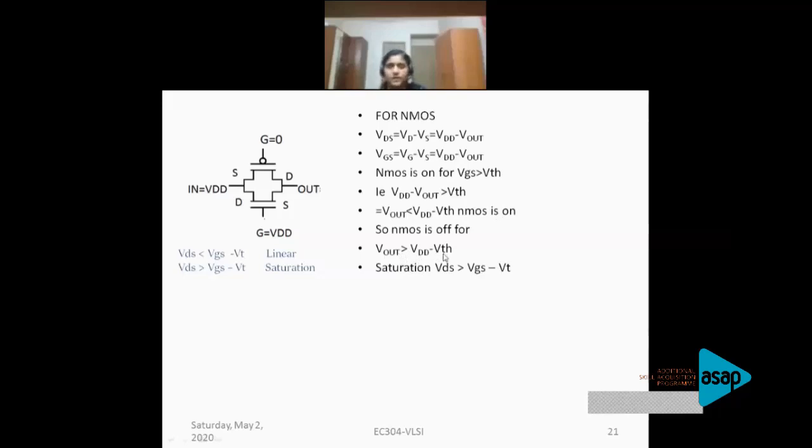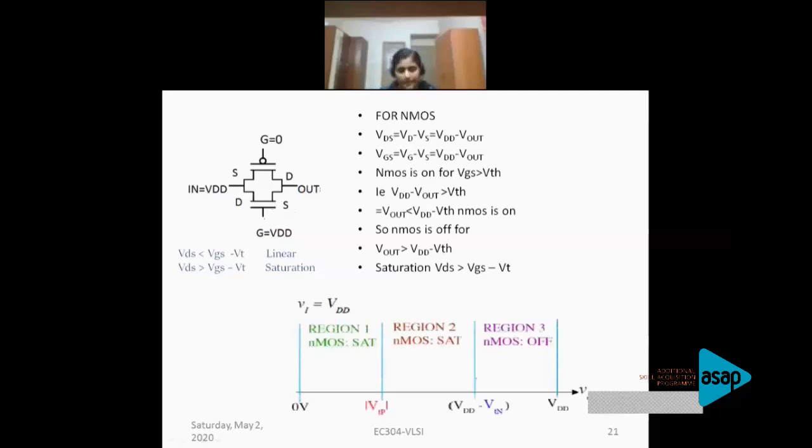So that is what we have concluded. Those are the two regions of working for an NMOS. Now I tried to plot that as a graph here. Towards the x-axis, what I get is VO, or your Vout. I've marked 3 points over here. This is the mod of VTP, mainly for analysis of PMOS. The one which relates to NMOS is VDD minus VTH, that is what we have seen here. And towards the VDD, the maximum output value that you can have is towards the VDD.